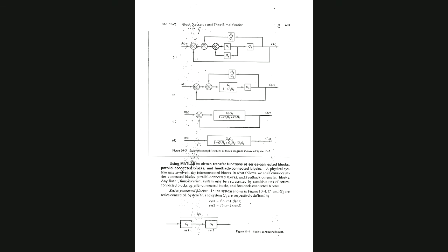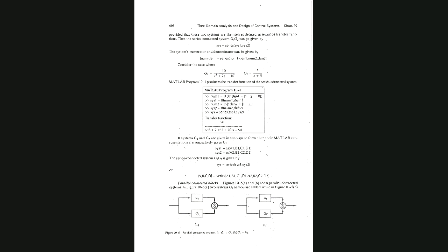Okay, we can represent block diagrams in MATLAB, as I have said. Series blocks, for example, can be multiplied with each other by saying series, or you can just use the multiply operator. That made it a little bit easier. For example, the series gives you the following. Skip this transfer function, the state space thing, we didn't learn that.